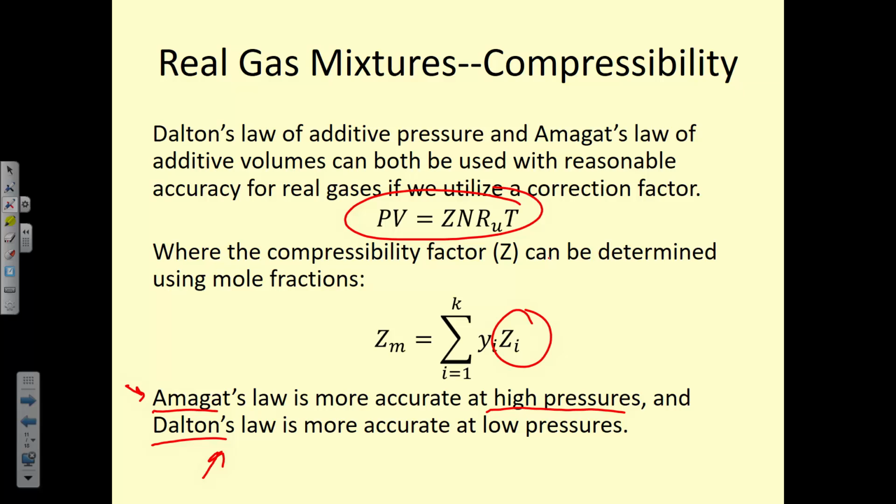So you can see how if you're operating with ammonia, you're going to have to be at a very, very high pressure to be far away from that critical point. So you kind of have to play with it. And in any case, you can always treat it as an ideal gas, figure out what your Z value is and see how far off you were.